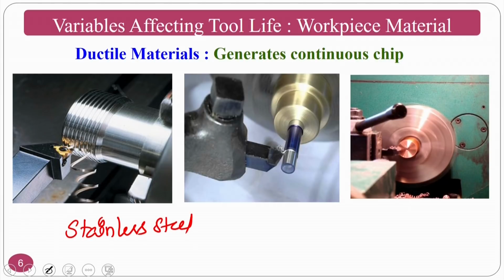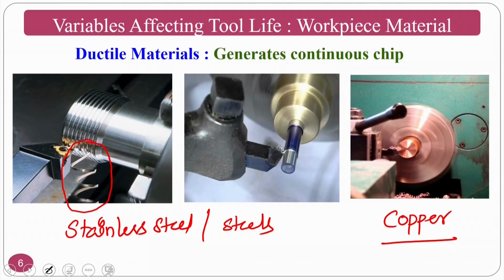This is stainless steel only. This is the copper. Okay, so the stainless steels are the iron based steels. Machining this normally generates a continuous chip. As you can see here, it generates continuous chips. Most ductile materials generate continuous chip, because of which tool life...